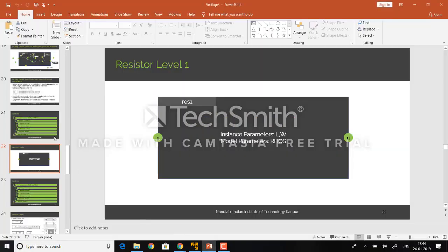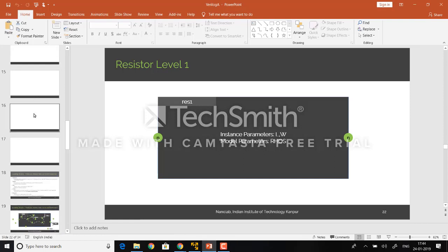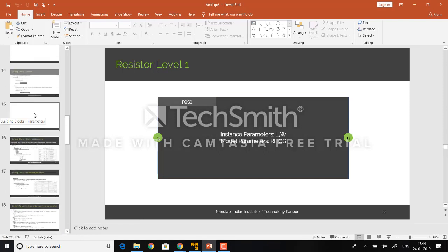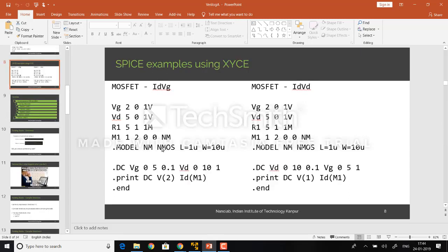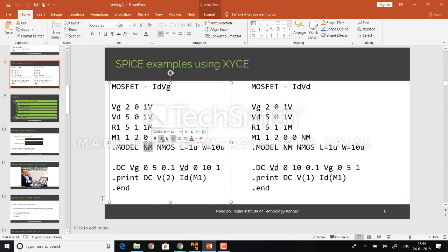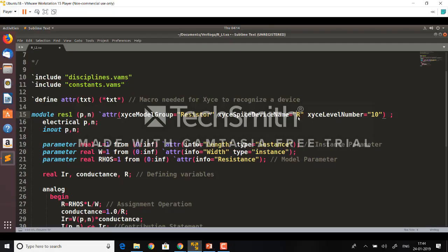when we did MOSFET. When we did a simple SPICE example of a MOSFET, we did this. For example, here, see, what you defined was M1 was a MOSFET with 4 terminals. Then you named it something. Then you called a model statement with the same name, and then you had this NMOS, right? An equivalent word here would be R. You can name it anything. You can name it maybe RES. Okay. For now, I've named it R.